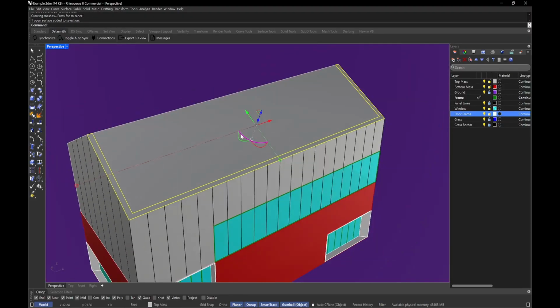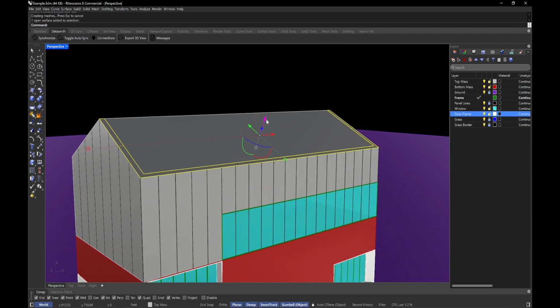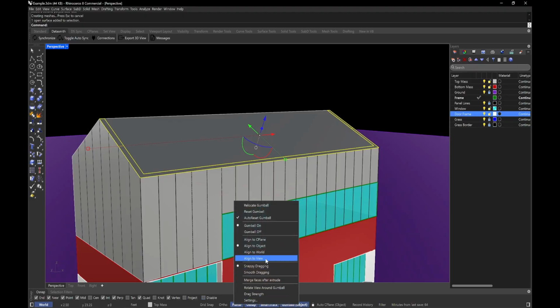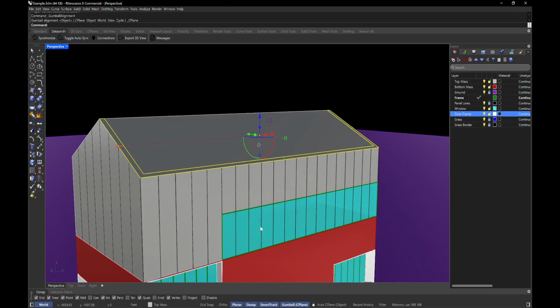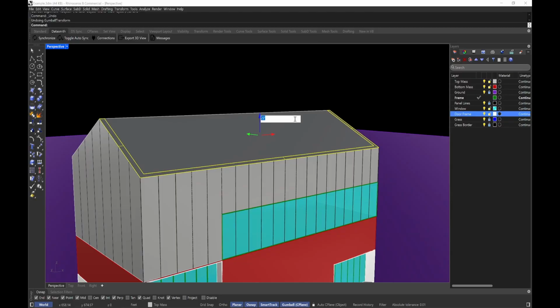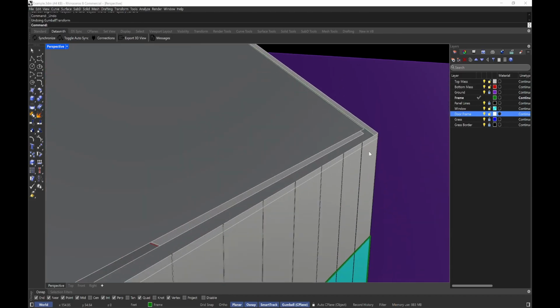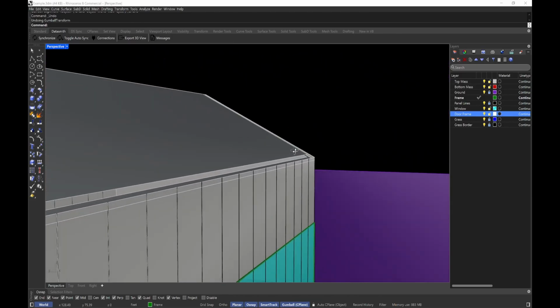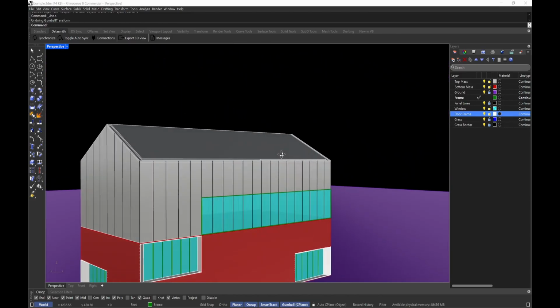And let me just push this down. I don't know. I'll push it down. So right now my gumball is oriented, I think, to object. If you see down here, gumball, it's oriented to object. If I do C plane, it means it's oriented to the world plane. So it'll go straight down. So let's go down, I don't know, like -5 inches. Ooh. Yeah, there's still a glitch in Rhino where if I do the negative, it still goes in the opposite direction. We have to do it twice. It's kind of annoying. So you see, I want something that reads like that.